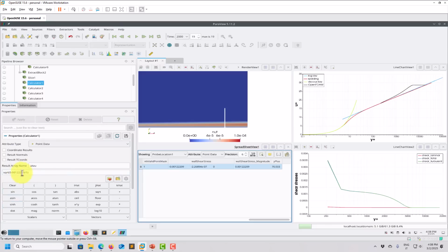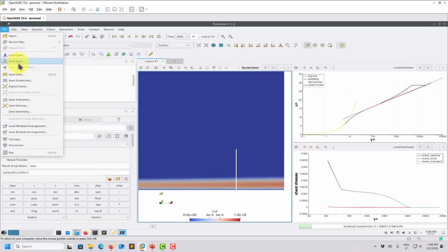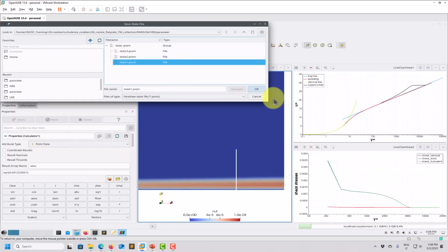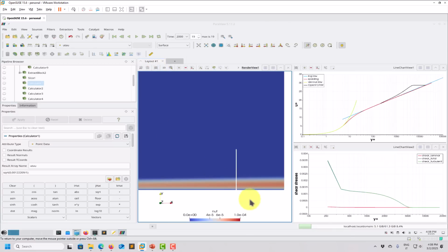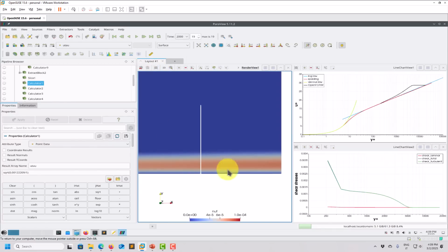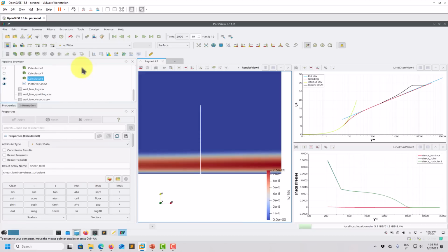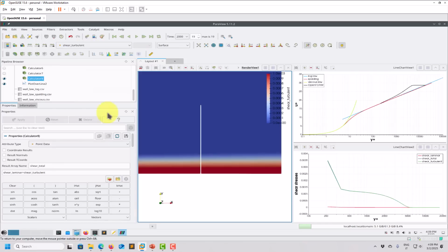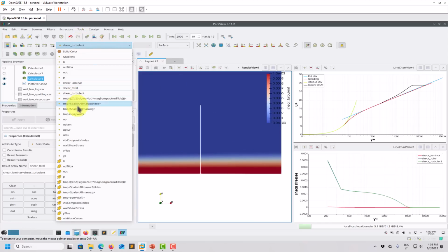So see that small differences can have a large impact here, in particular in the buffer layer, the most energetic one. But still the results are correct. And let me move here. And if we look here, we have nu, and as we mentioned, it tends to peak in the boundary layer, the maximum value of nu. So we have that behavior here. Okay, we can observe that, but also we can take a look at nu tilde. Okay, so our nu tilde also peaks somewhere there. And well, we have the laminar shear, turbulent shear, that should all be there, and all the other quantities.